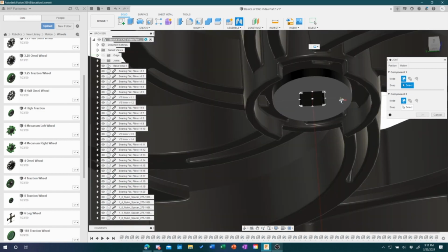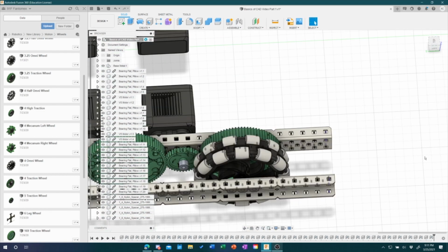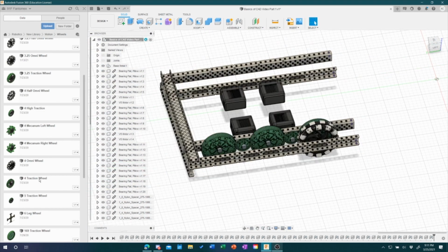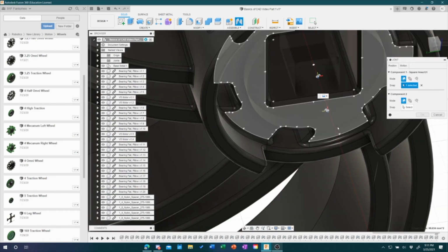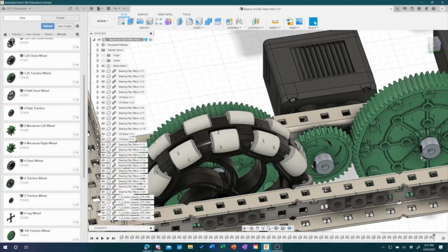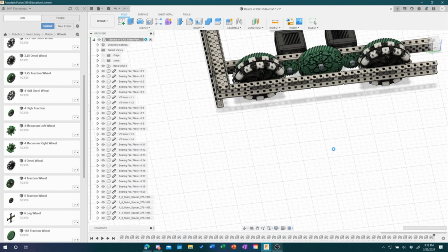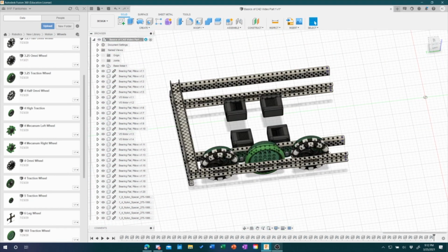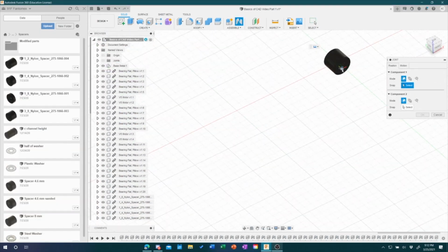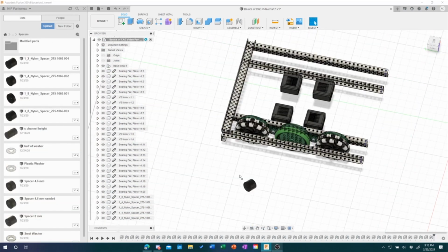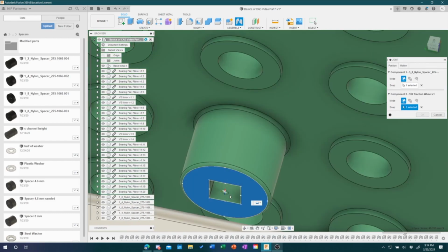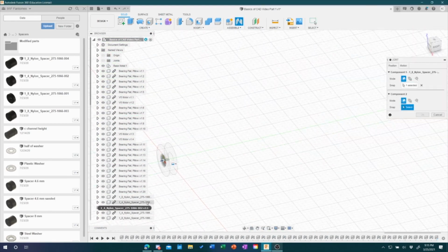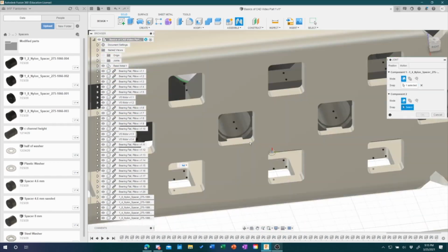Now, like the gear, drag your wheel of choice, in which my case are 4-inch omnis and 4-inch traction wheels, which have been modified and are now dubbed by the VEX community the 169 traction wheel. This is a difficult component to make as it involves chain, but in a later video I'll show you how to make it. Now, you want to fill up the rest of the space with spacers, and in this version I do not add axles as I find them unnecessary and difficult to add. Now you can just repeat everything you did on the left hand side.